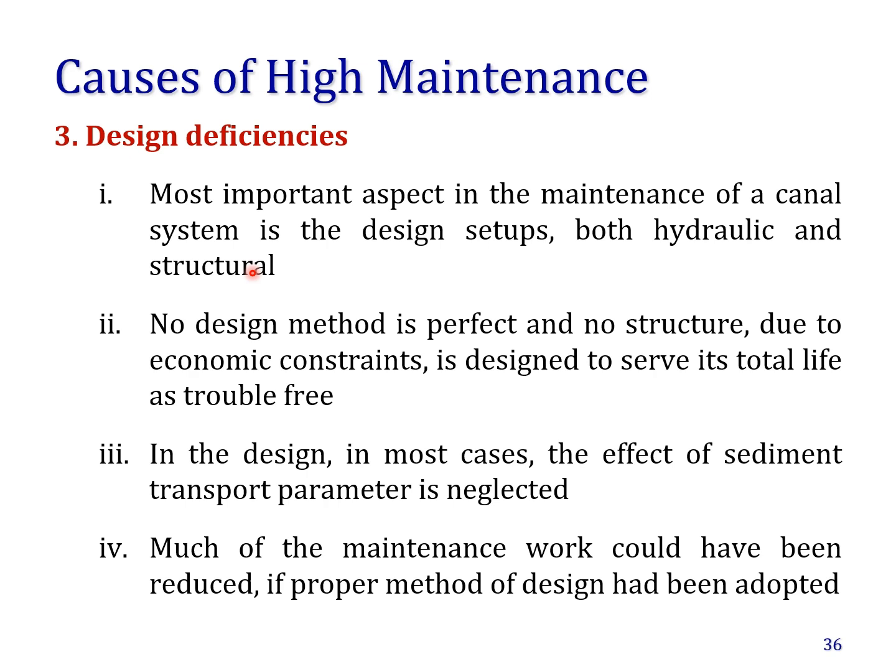So when the canal runs, you will see that things are different from the design, and that will cause high maintenance. In the design, in most cases, the effect of sediment transport parameters is neglected. Much of the maintenance work could have been reduced if a proper method of design had been adopted.